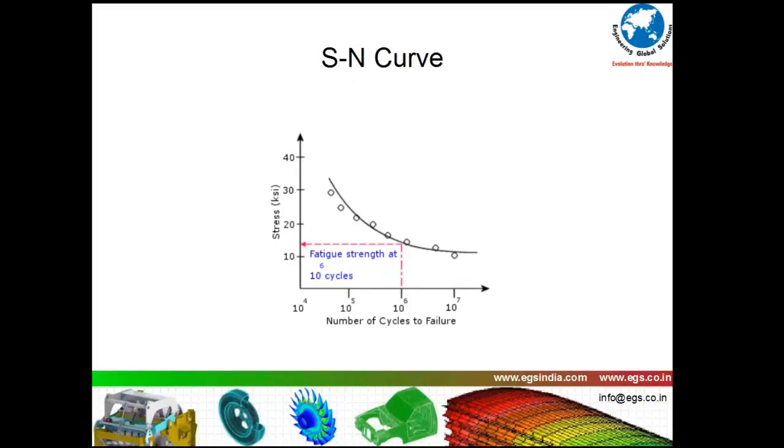If you take the case of a wheel, when you roll the sheet metal into a wheel cylinder, or for example a pressure vessel, the exterior fiber goes through tension, the internal fiber goes through compression, and when you have bent it, rolled it and seam welded it, it is going to be in a very high state of tension, much beyond the elastic strain.